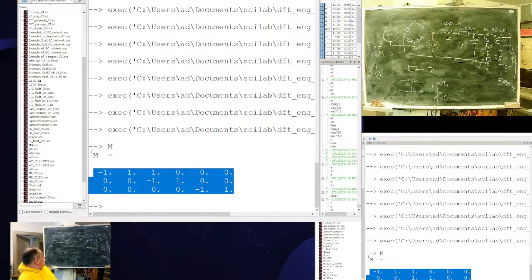So first I start from the main diagonal. What do I have in branch 1? 20.35 active ohms, yeah? Plus j omega multiplied by 100 millihenry, it's 0.1 Henry. Do you understand what I'm doing?